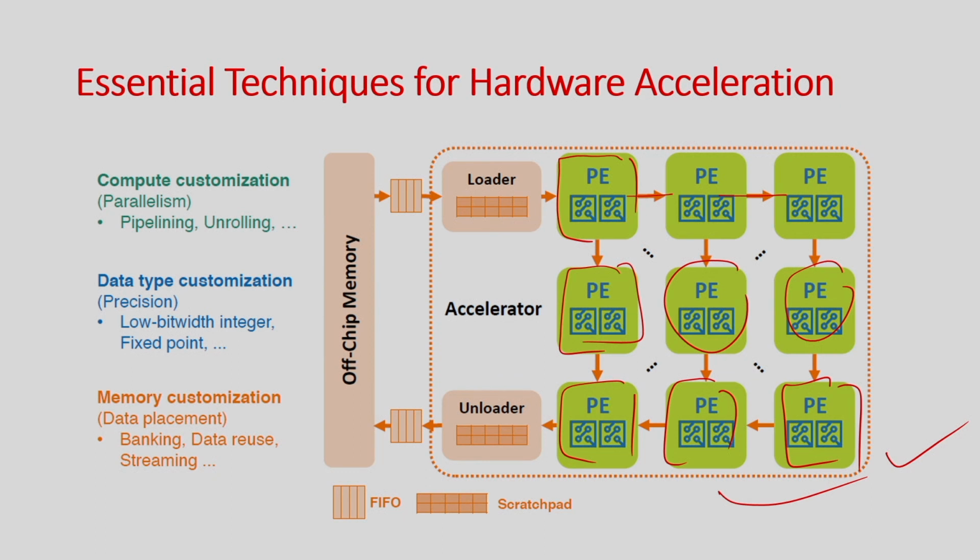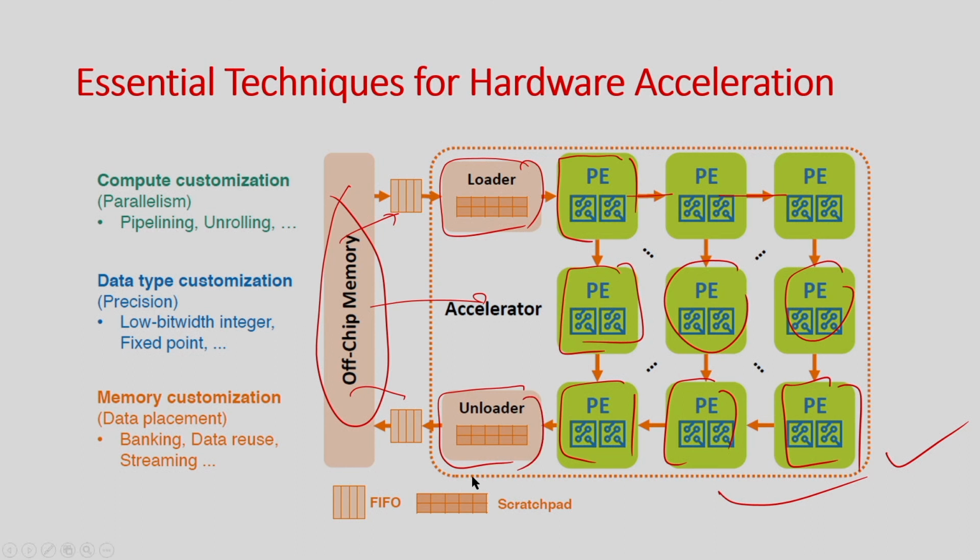And then basically your data is in some outside memory, and you feed it through a FIFO channel to the hardware accelerator, where you store the small components in memory, say a local RAM. So, this is the loader, and the output you can also put in another RAM, and you can serially send it outside. If you map your application into this kind of architecture, then only will you get the maximum benefit, right. This is what you want at the hardware level, which is basically efficient.